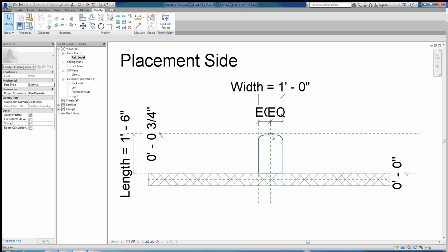Okay, so we've created our extrusion for our water fountain, just kind of the body of it. We've made a button. Let's go ahead and make a void for this water fountain as well. And this void is just going to be kind of a standard box inside of this water fountain here. I'm just going to make it so our void is an inch offset on the left, on the right comes inward 3 inches, and then comes inward here maybe an inch or so below the arc.